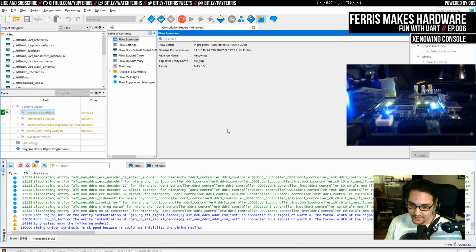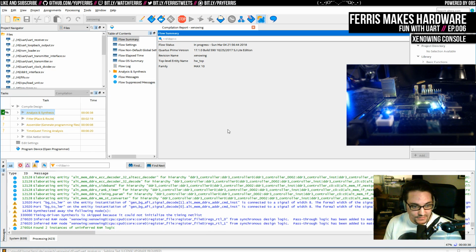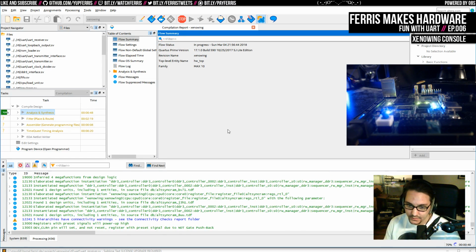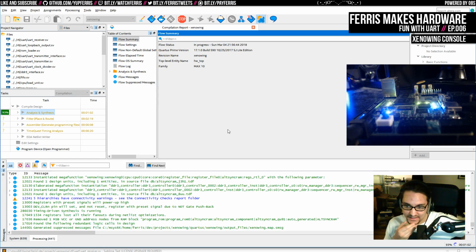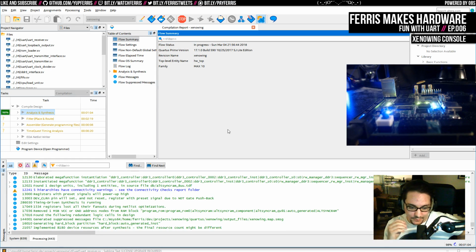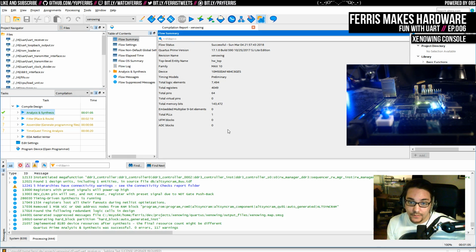The same thing here that's pulling off this FIFO and doing the loopback could just as well overwrite the ROM. And in fact, I probably won't even use a FIFO for that because it'll be so simple. And it'll be basically instant. So yeah, I think I'll do it whenever the ROM loader is in its receive data state, it'll soft hold the CPU and the rest of the system in reset, and then just incrementally update all the bytes. It should be really basic how that works.